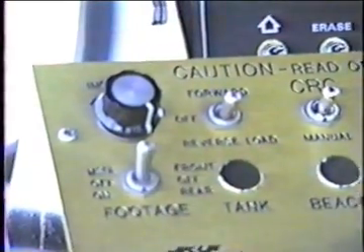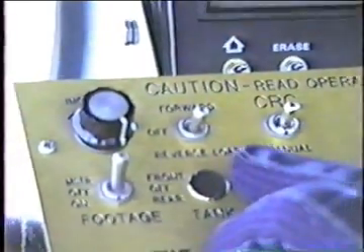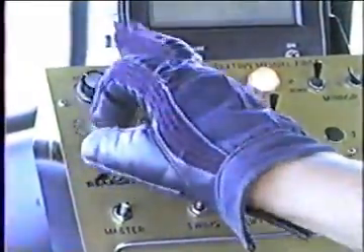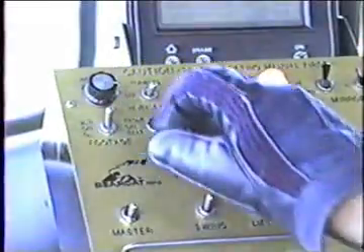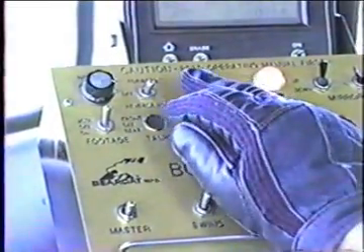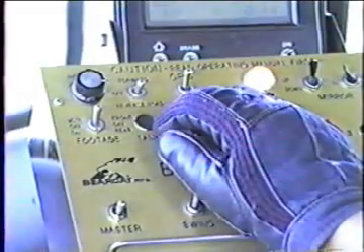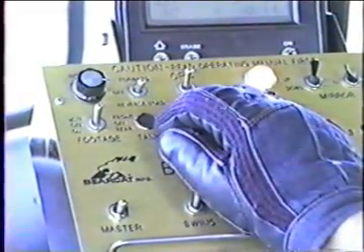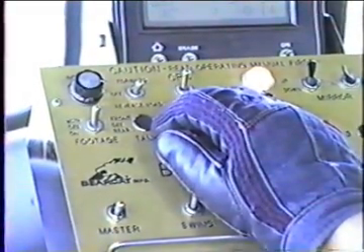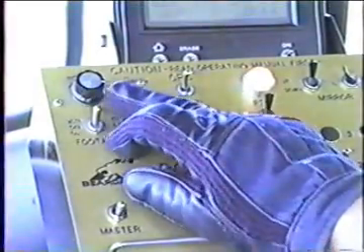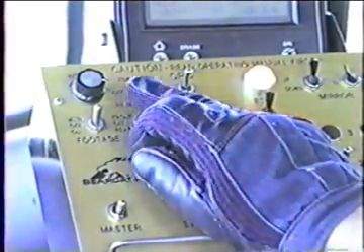Okay, now we're loading in reverse. We've got it in manual. The pump is running in reverse, and we run it up to full speed to load it. When we get done loading, simply switch this back to the CRC position. Now the pump goes back into the circulate condition. We're done with the manual control here, so put it into the off and put it down to the 0 speed position.